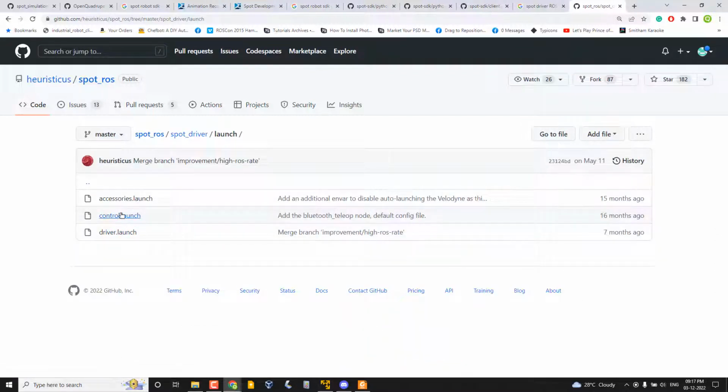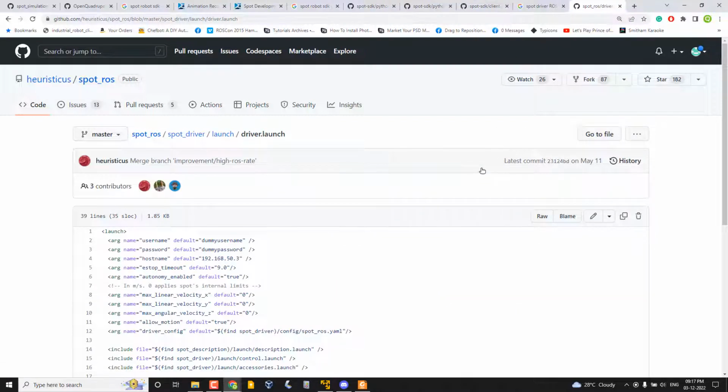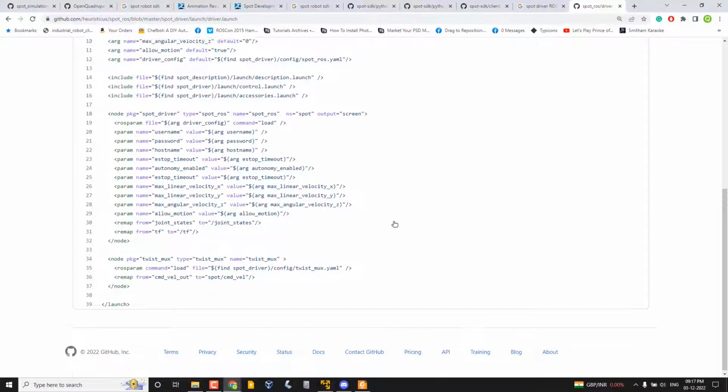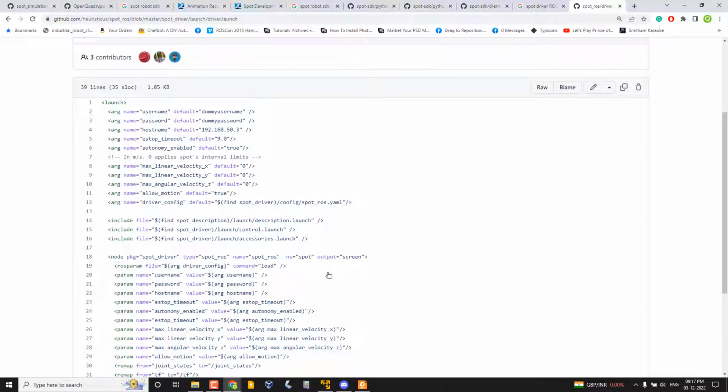Recently I worked with a robot from a company called Kinova. It's not Jaco, I forgot the exact name, but the company name is Kinova. They have the same kind of SDK and driver, so when you run the ROS driver, it is exposing all the APIs in the SDK. In order to start the robot, you can simply call a service. In order to move the robot, you can simply call a service. I mean, everything is exposed as a service. So that is the driver.